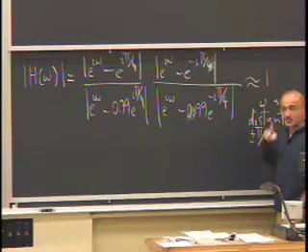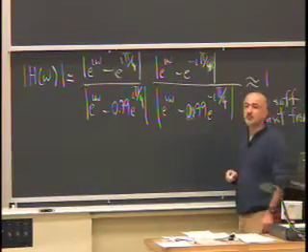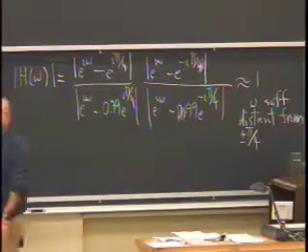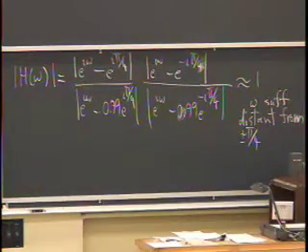Is that clear? Question? You now have two notches. I have two notches, yeah. Is there a way to rectify that so you just get the pi over 4? That's usually, for practical purposes, not a problem. So usually if you want to notch out one frequency, typically you want to notch out the negative of that frequency. Otherwise, you'll have trouble with things like cosine pi over 4 n. Your boss wants you to notch out not just e to the i pi over 4 n, but cosine pi over 4 n. That then dictates that you need another notch here.